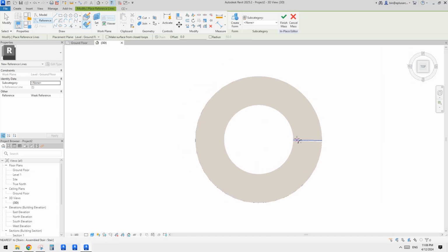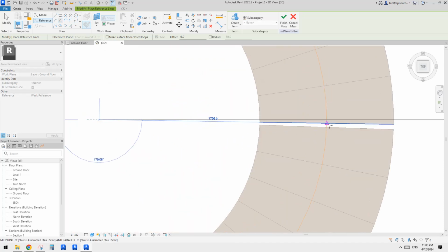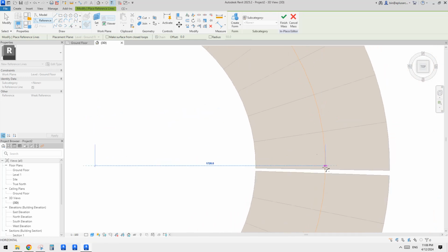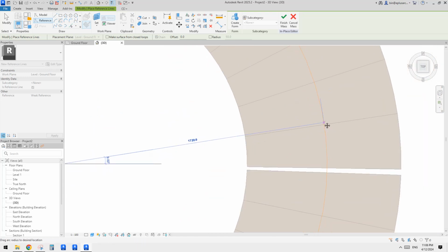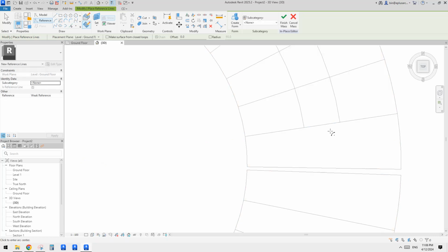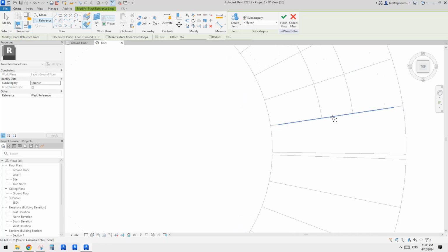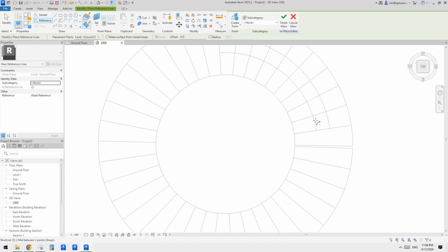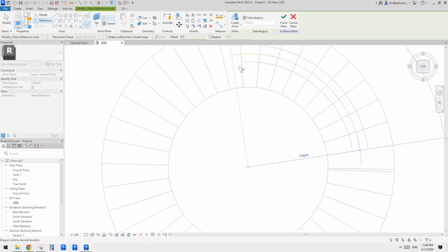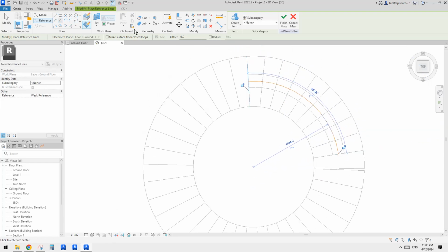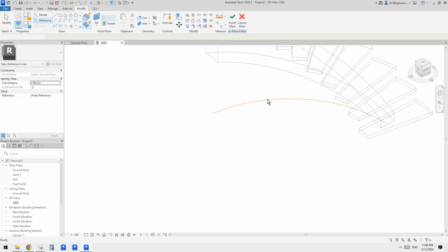So we're going to just type SC to snap the center point of this stair. And then we're just going to start from the same, oh, not here. Oh, maybe here. Actually, can't really see. Or type WF. It's actually overlapping, so that's fine then. So let's just do it again. SC, center point, and then pick this point, go up. Maybe I'll just stop at this point as well, right? And then go rotate this. So now we have this path.